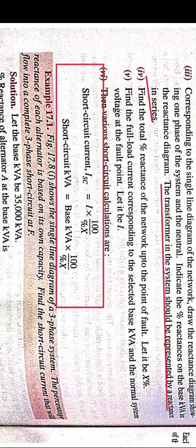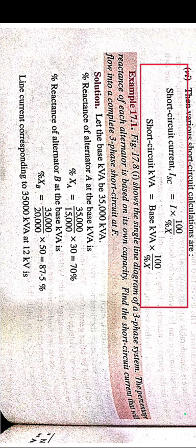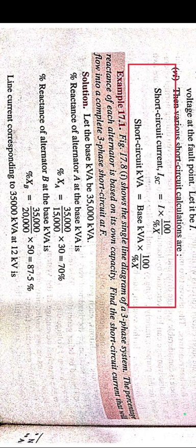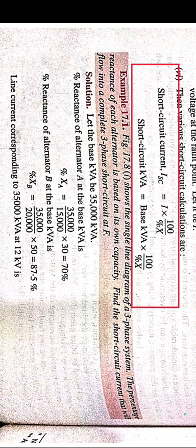Short circuit kVA is equal to base kVA into 100 divided by percentage X.